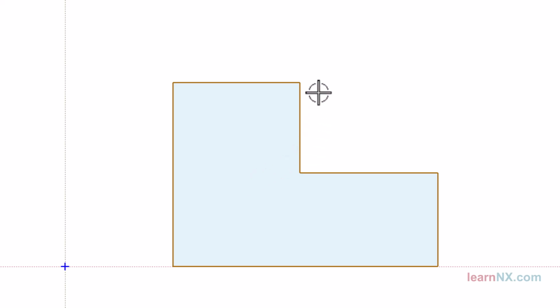Normally not, because the analysis only starts when an object has been selected. But then the symbols show which objects would be affected by a change. In a complex sketch, it is clearer to see only the constraints that are affected by a change than if all constraints are always displayed. But there are also permanent constraints that we are still learning about.